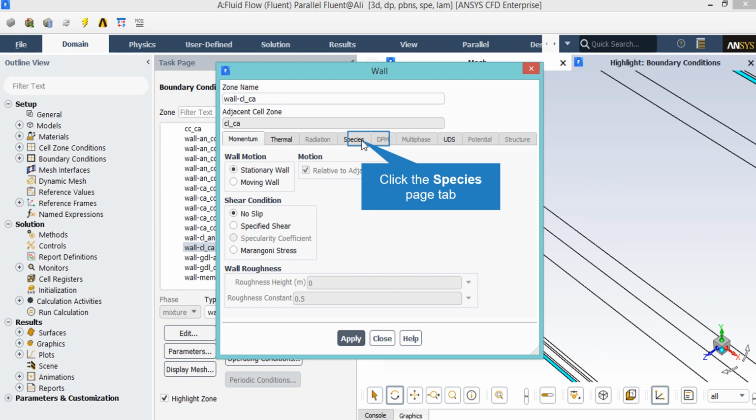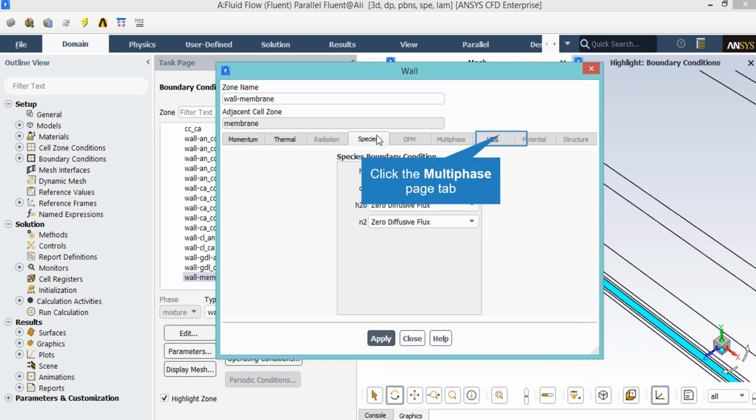After clicking on this wall boundary, you can see that heat flux thermal condition has been defined with a heat flux rate of 0, which means that this wall is adiabatic. And if we click on UDS tab, you can see that under the user-defined scalar boundary condition of electric and protonic potential, the setting of a specified value and a specified flux respectively have been defined.